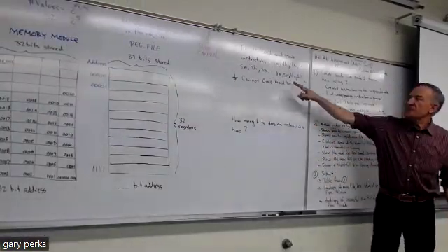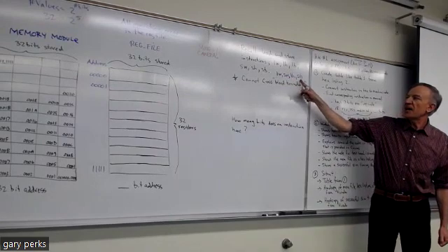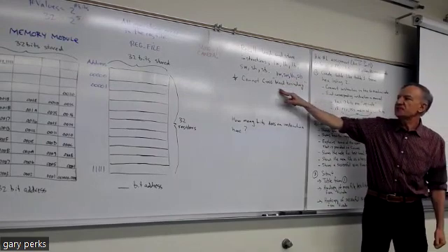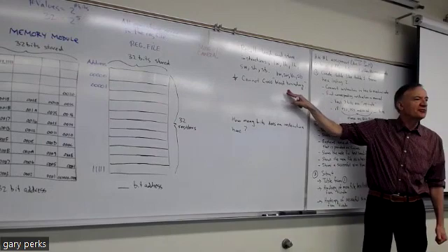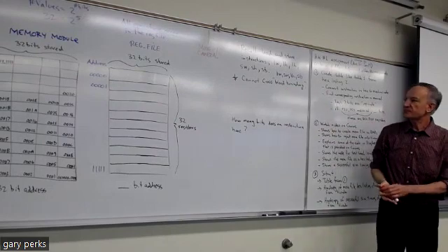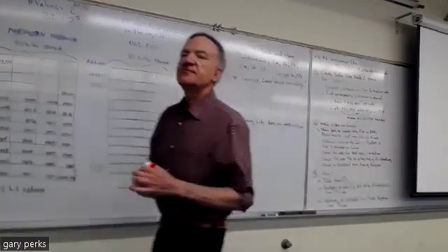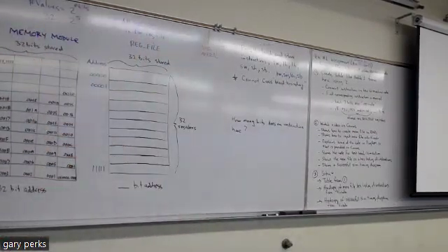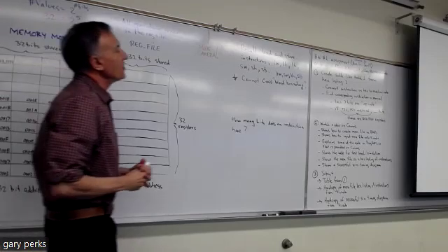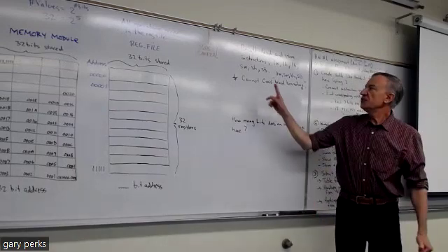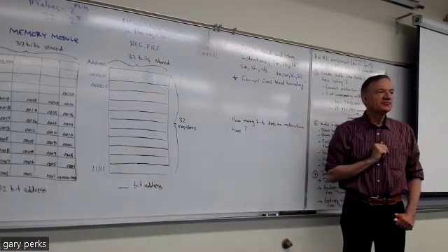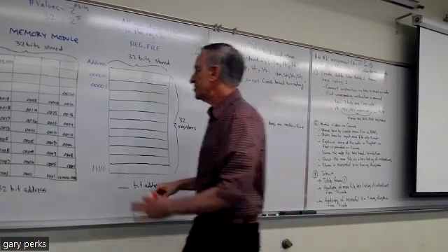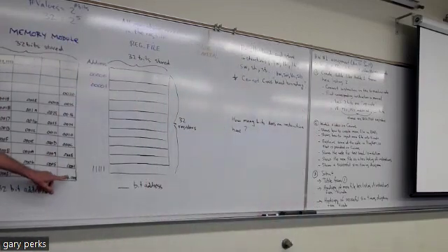Yeah, so anytime you're dealing with a word or a half word, you have to be mindful of not crossing a word boundary. So let me talk about what that is. Okay. Well, as we've said, with the memory module, every byte has an address. So if I go to either load or store a word, the addresses that I can use could be any of these addresses over here, because how many bits is a half word?